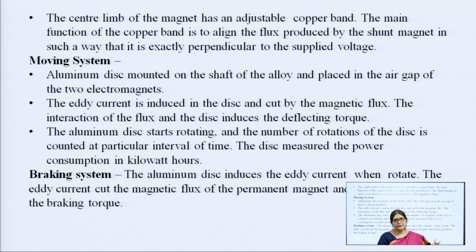Then the braking system, which I have already discussed. The aluminum disc induces an eddy current when it rotates, and this eddy current cuts the magnetic flux of the permanent magnet, and then it produces a braking torque.